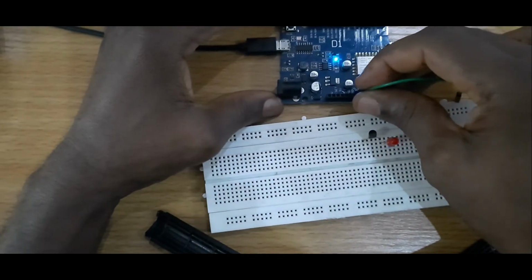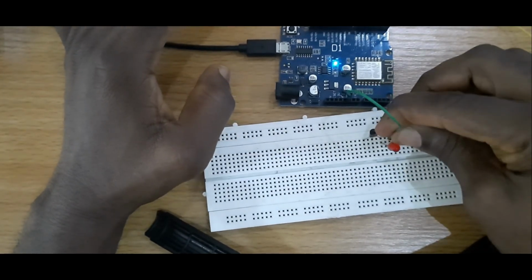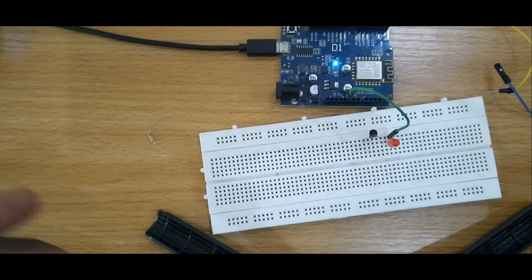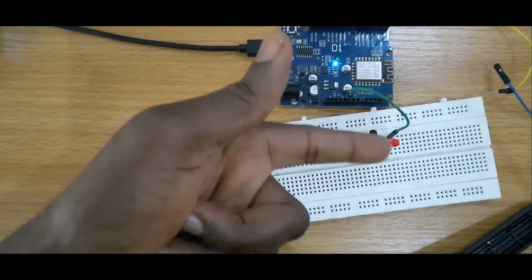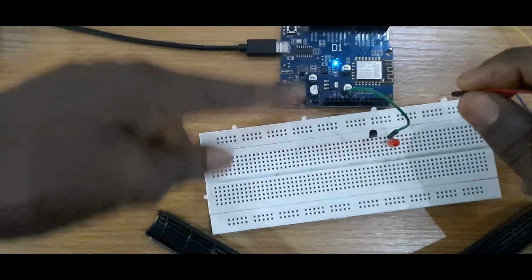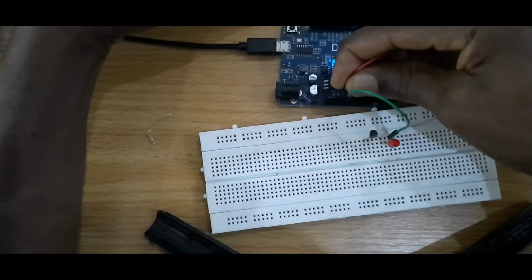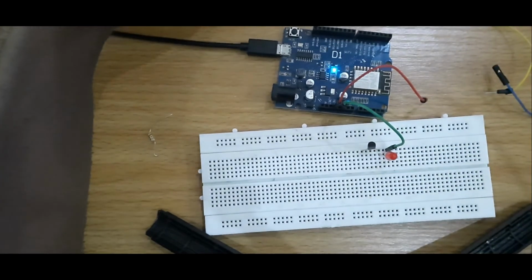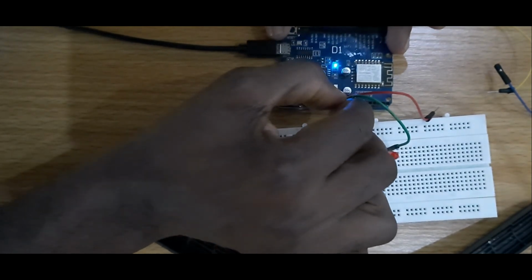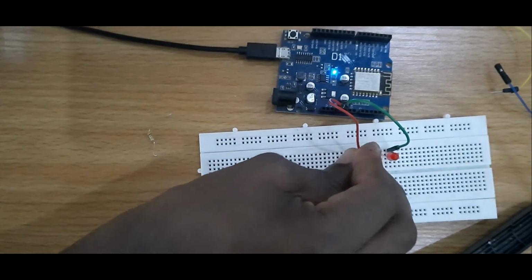So I'm going to connect that to ground. Surely you wouldn't expect it to come on now. I would like to use the 3 volts to power that. There's a 3 volt power that will connect to this LED, and I'm getting that from the board. I have a 3.3 volt logic over here that I could use. Got the 3.3 volts connected.